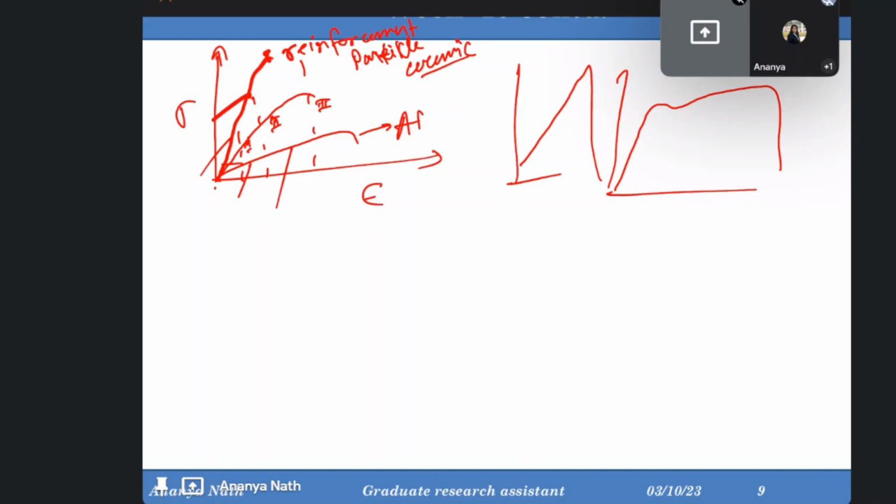That's what has been taught up to lecture 3. Then from lecture 4, the strengthening mechanisms were demonstrated. So we do not really have to go for any strengthening, because already we are mixing some ceramic or reinforcement particles which are already having some more hardness than the parent metal. Otherwise we would not mix those things. So if the mixing is proper, well distributed, then we have already achieved one stage of the strengthening.